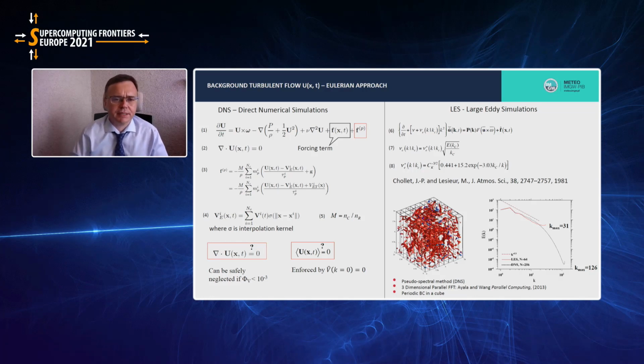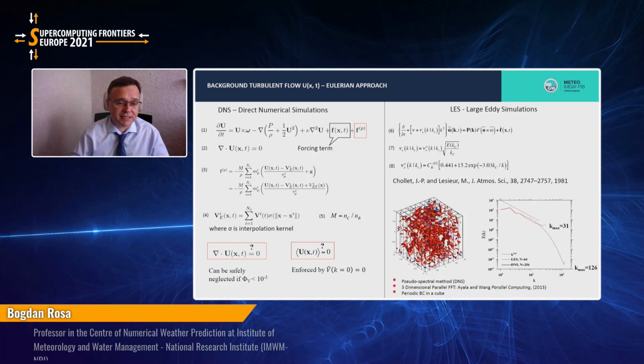So our research tool is numerical simulation. We use the standard Eulerian-Lagrangian approach. For modeling turbulent flow, we use the Eulerian approach, so we solve the Navier-Stokes equation on a regular mesh. Equations 1 and 2 are the standard Navier-Stokes equations in compressible form.